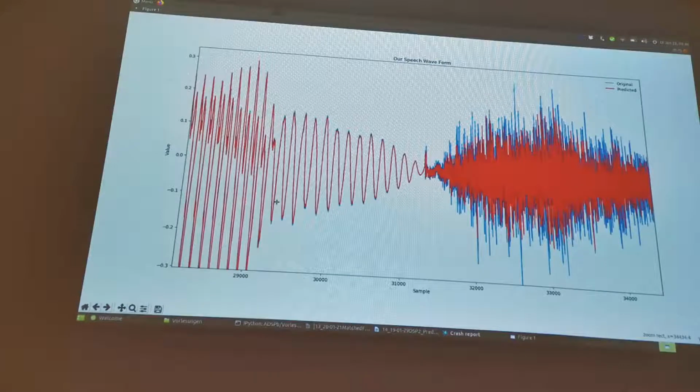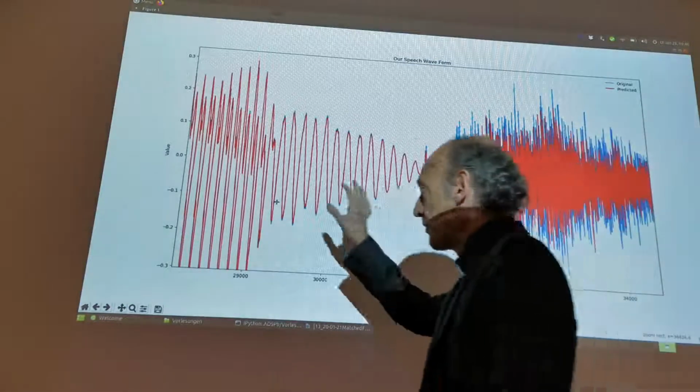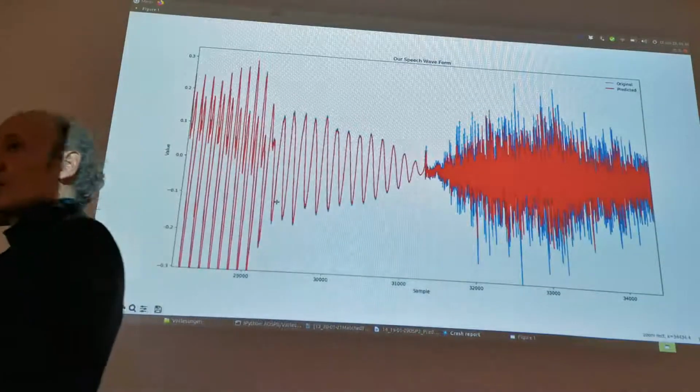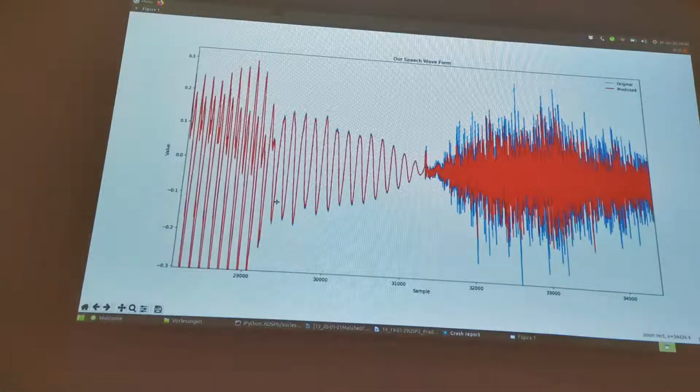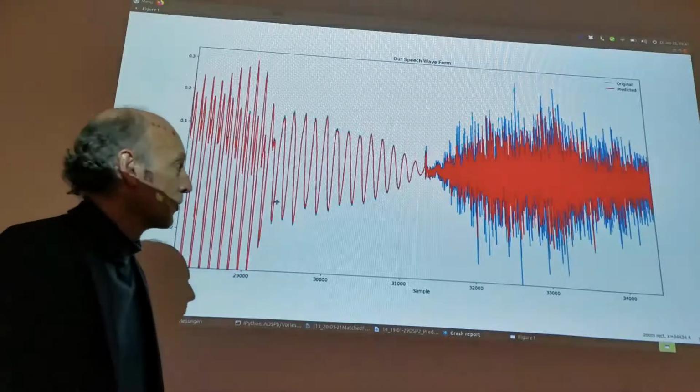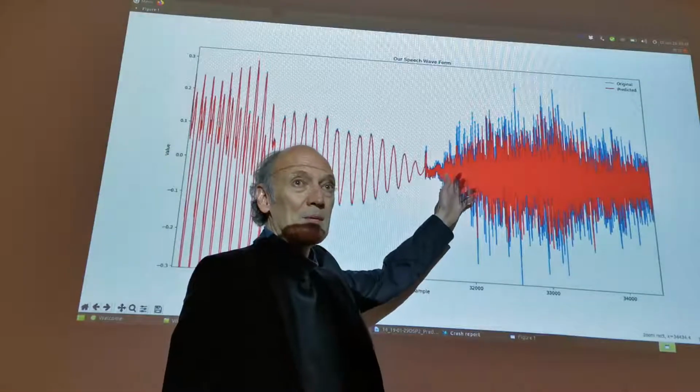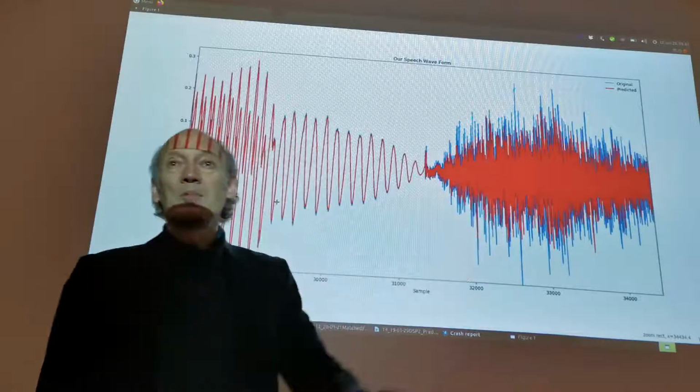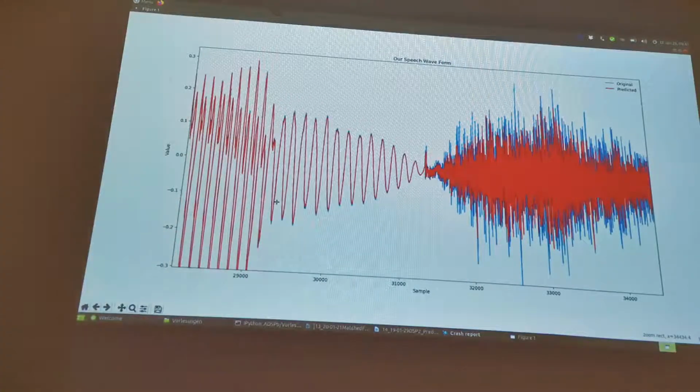And that's a problem in general. When you have tonal parts of the speech here, that makes it quite easy to predict for the predictor, because it's periodic and it repeats. But then if you have plosive parts like S and T, it's more like a mix of noise and oscillations, and the noisy part is hard to predict. So the noisy part is basically filtered noise. Right?